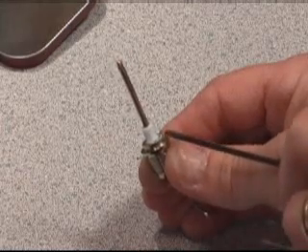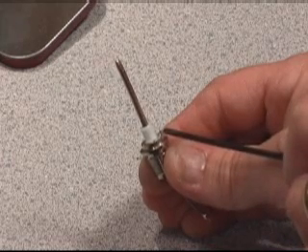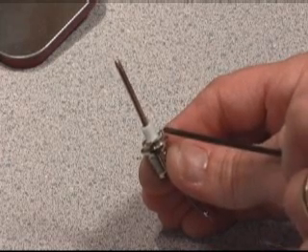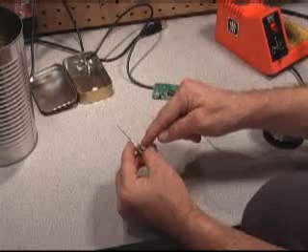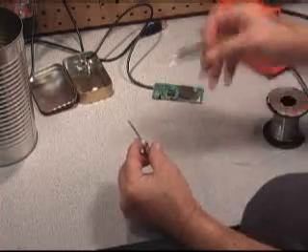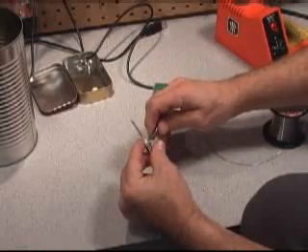Well, Darren, if you look here, you'll see where I pulled the wire through the little hole and soldered it. And the reason I did that was to keep the impedance of the antenna circuit as close to normal as possible. If I had exposed more of that center lead to run up to the element, then it possibly could have changed the impedance there. And I wanted to keep it as close to standard as possible. Therefore, the shield was right at the bottom of the antenna element itself, and that's where I soldered it.